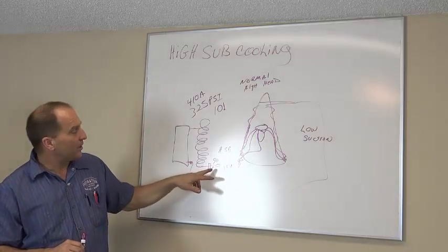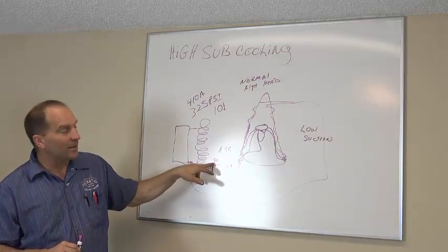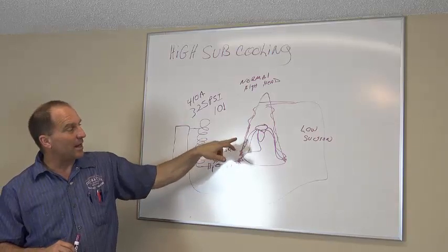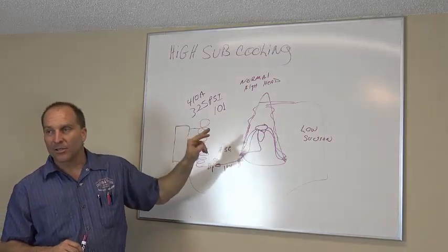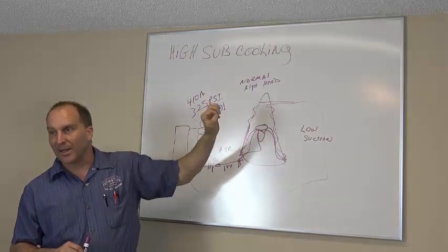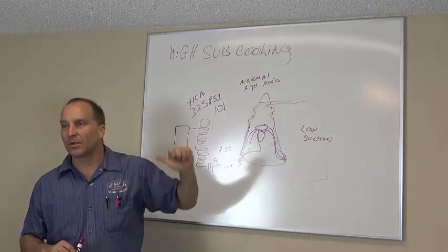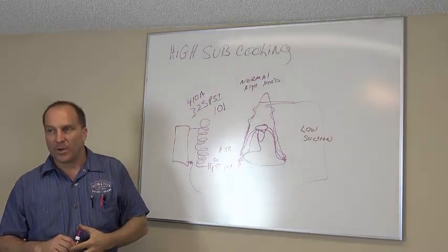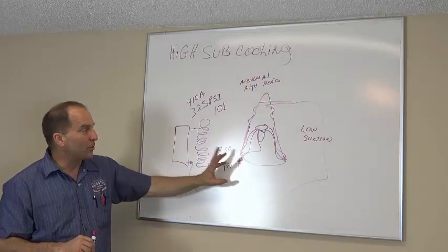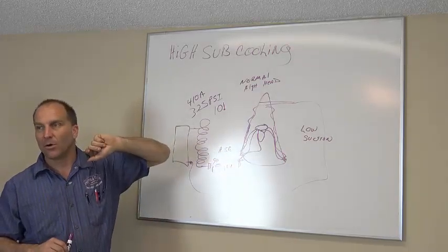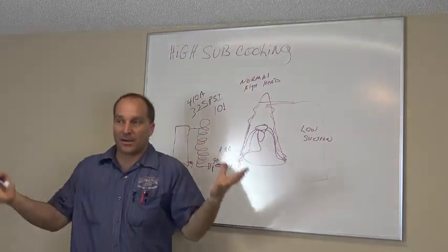If you take the temperature of your liquid line and it's reading 90 degrees right here, and you go inside to your coil, and as your 3/8 line is going into your coil, you read the temperature on that line there, you may be cooling it down a little bit more because you're picking up heat from outside, right? Or are you dispersing heat outside?